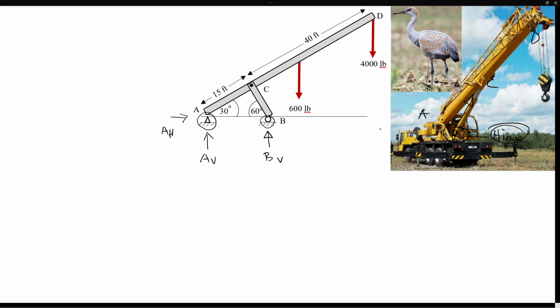So at point A, here at the contact at the truck bed, also the cylinder is attached to the truck bed. So there is not a rolling contact right here. It is actually a hinged connection. So when you have a hinged connection, then you also have a horizontal component there too. So now you have four variables. You only have three equations. So you won't be able to solve just by simply applying the techniques we have discussed so far.